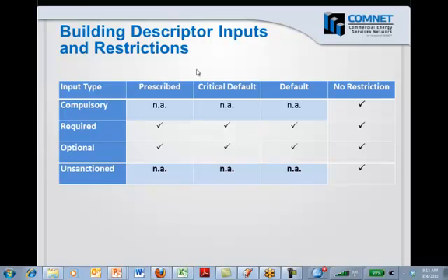An example of a critical default would be plug loads. Plug loads should generally be the same between the rated building and the baseline building, but we have a procedure where they can be different, and you can take credit for reductions in plug load. But when you override that plug load default, you would need to provide some documentation and justification.